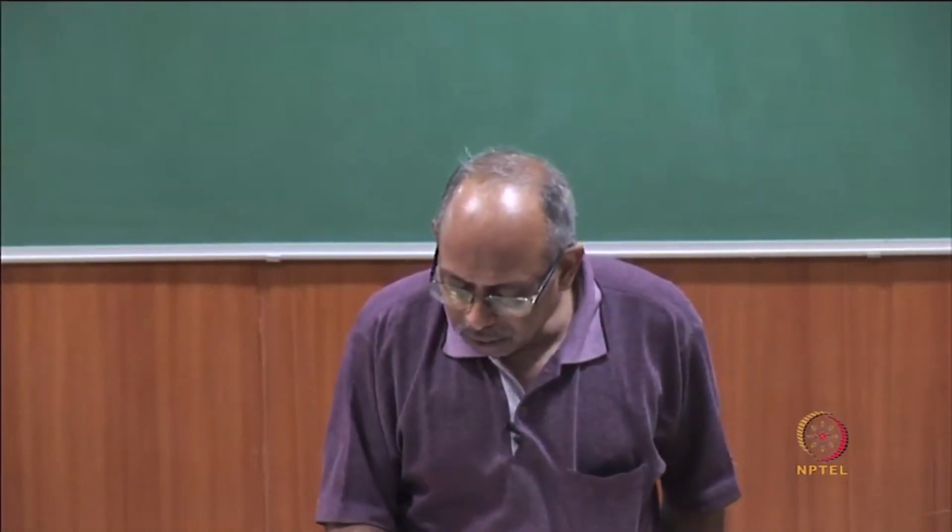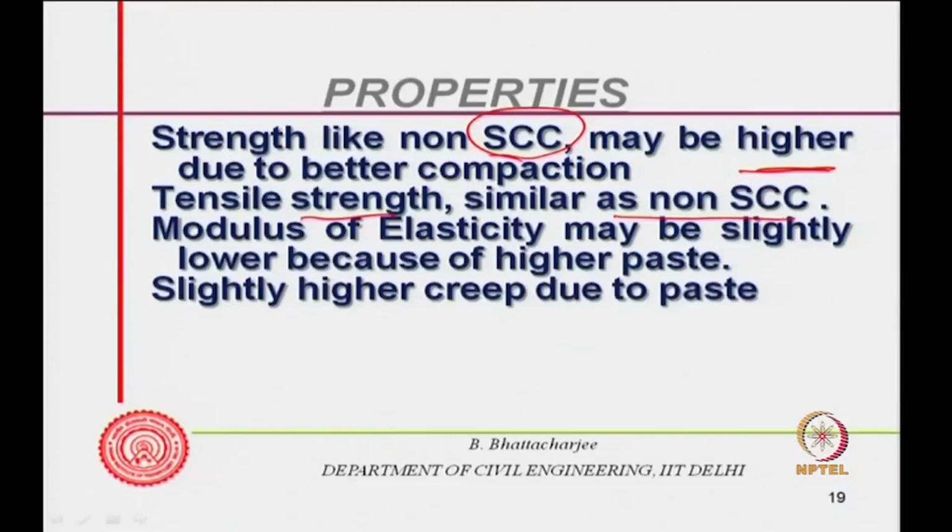There should not be any question on tensile strength, it will be similar to non self compacting concrete. After all, we have seen that empirically tensile strength is related to the compressive strength. So, therefore, there is no question. Modulus of elasticity may be slightly lower because of higher paste content.